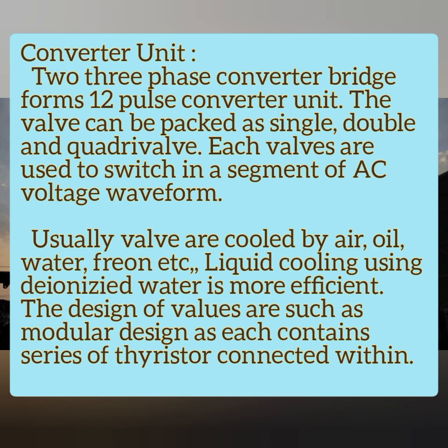Usually valve designs are modular, where each module of the valve contains a series of thyristors, like a few thyristors combined in series to form a module. Likewise there will be modular structures, and the total modular structures form one valve, the full valve actually.